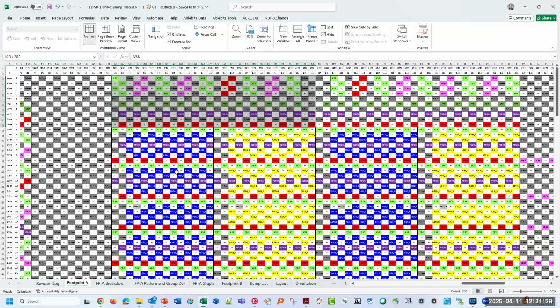If the pillars change in size, you want to have the dimensions of the pillars on the side. Do you want to have in the index the method of bonding between one die and another die? For example, is it through TSV vias or bump connection?